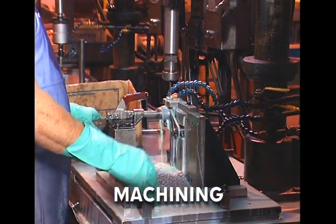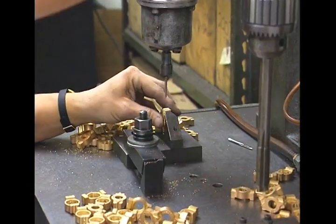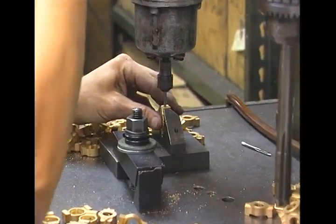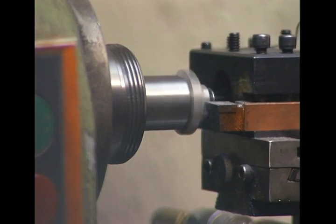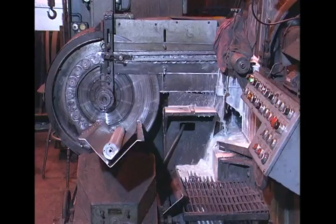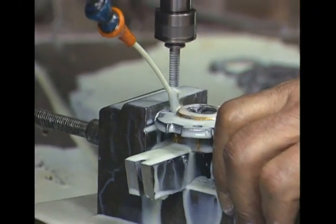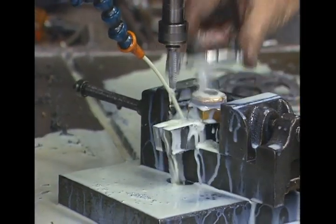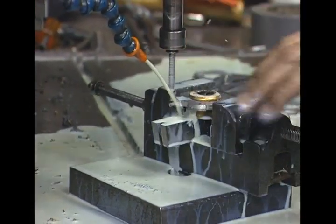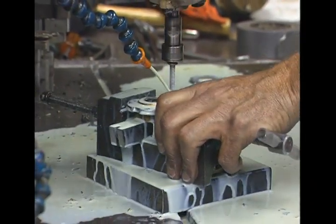Secondary machining operations are needed because side details, such as grooves and holes that are transverse to the pressing direction, are impossible to produce by the vertical action of mechanical pressing. These machining operations include turning, milling, grinding, drilling, and tapping. Choosing the proper coolant is extremely important when machining powder metal parts, especially for porous parts, because the coolant may be absorbed and react with the base metal.